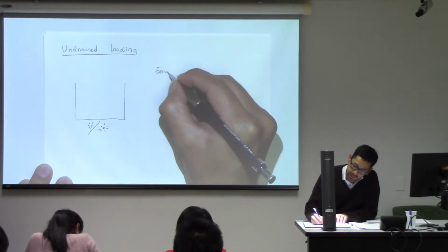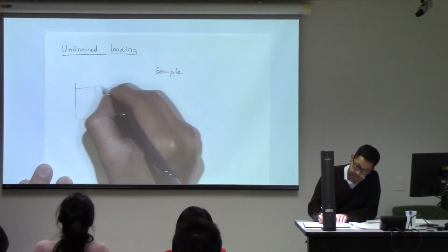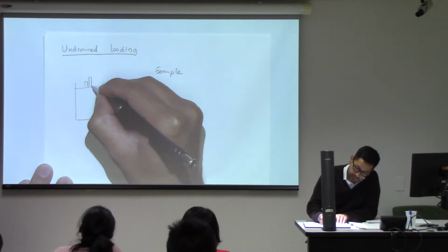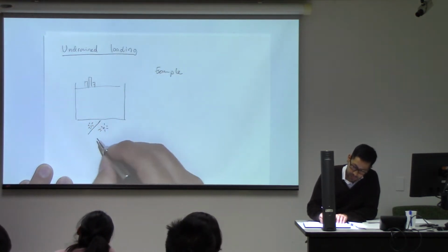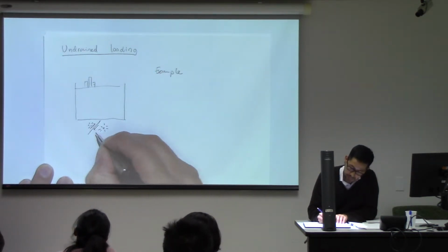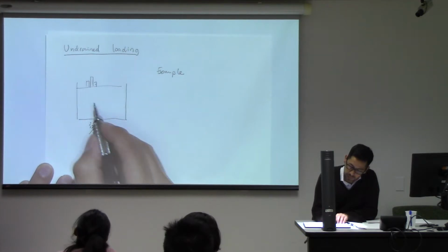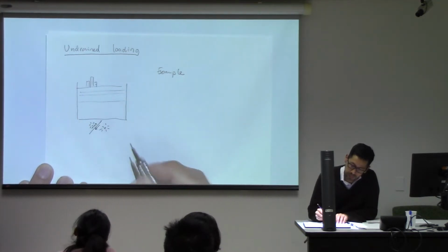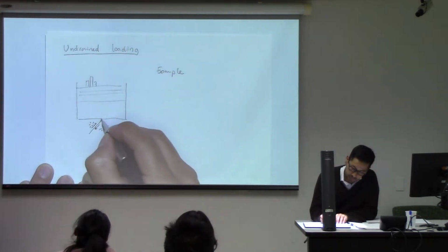Usually it's like earthquake loading, the sand's trying to consolidate. Okay. When it's vibrated, but the water can't get out from the pore spaces fast enough because the loading is so rapid and the water can't flow out.